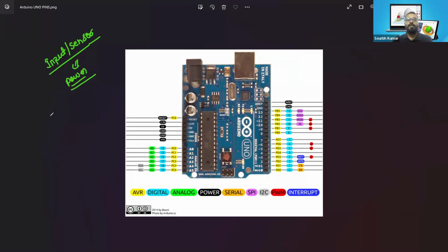If you look into any of the sensors like the IR sensor, the IR sensor has 3 pins in total. One is the positive pin, the other one is the GND pin, and the third one is the input pin for the Arduino. So it does require power to operate. So how will we get the power to operate different devices around, like the sensor device and output device?